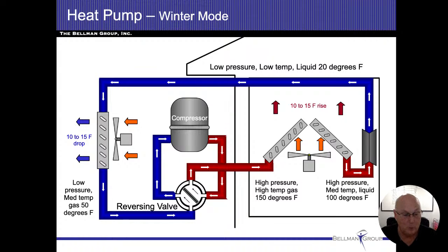I'm actually going to be discharging my heat on the inside. So as I'm discharging my heat, now what used to be my evaporator coil, it used to go from a liquid to a gas. Now it's going from a gas to a liquid. So it comes out of there as a liquid, hits my restricting valves, my capillary tubes, a reverse TXV, whatever. All right. It's going to lower the pressure. It's going to remain a liquid. And as we lower the pressure, we lower the temperature.